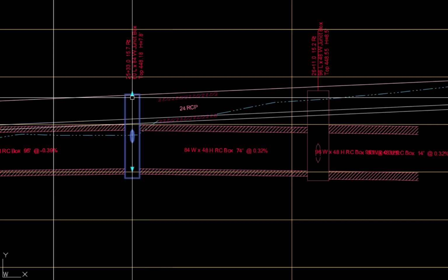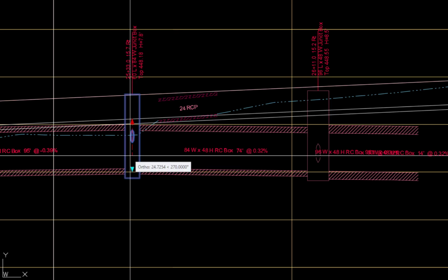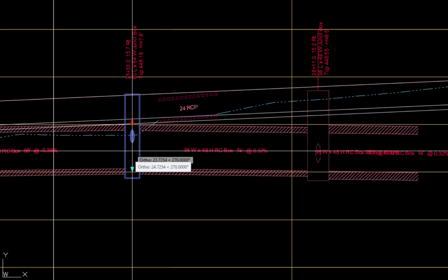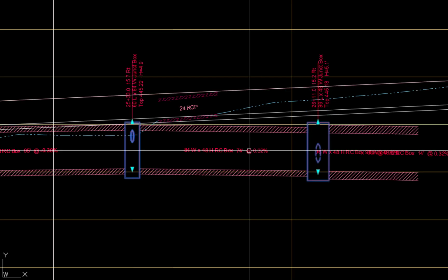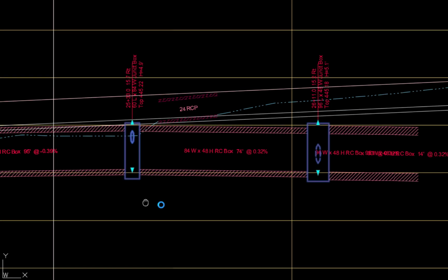Enter. Apply. OK. This is a junction box with a curb inlet installed on top. Pick the top glyph. Move vertical downward. The top cannot be moved below the top of the connecting RC boxes, and pick. Repeat the procedures for the upstream pipe and boxes.